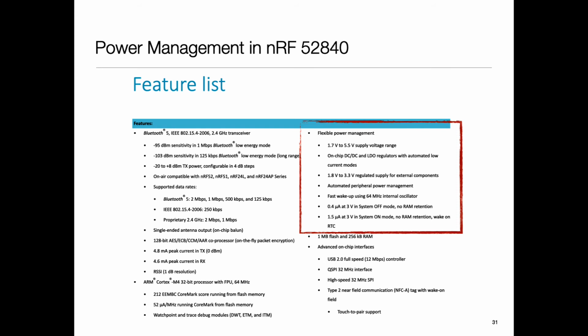Voltage, same thing, voltage regulator, right? There are capacitors in there and all need to charge up. So if you look at the voltage, it takes time to stabilize. So circuits have some time it takes, let's say order of milliseconds. Then there are other parts of your system, like let's say radio. If you put it to sleep, when you wake it up, it needs to resync with the rest of the system, like let's say to a base station and all. That can take time. These are sometimes just protocol related things. And finally, software. If your system boots up, then boot up it has to take time.